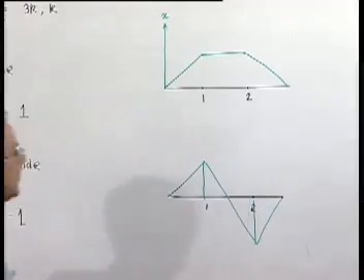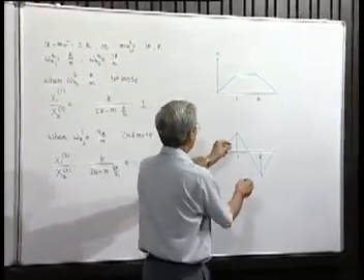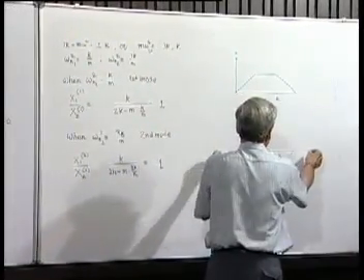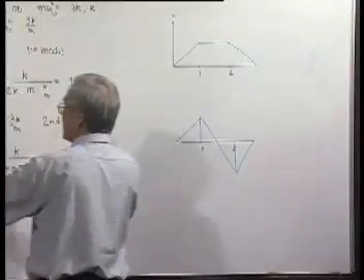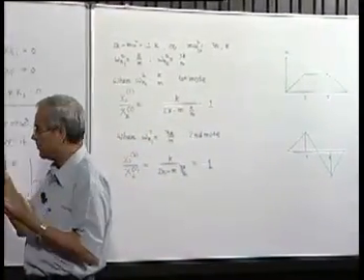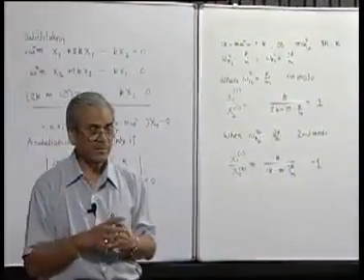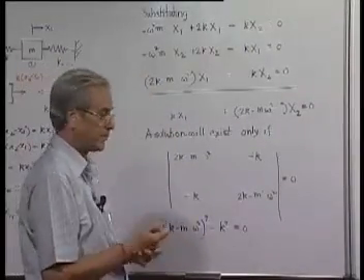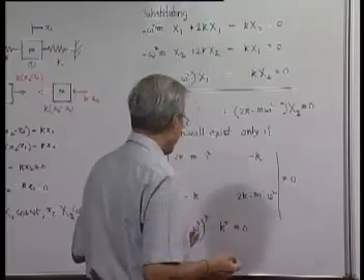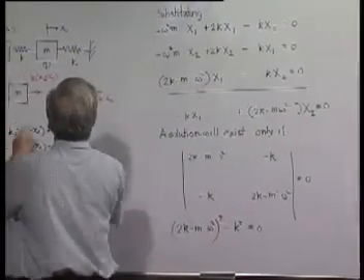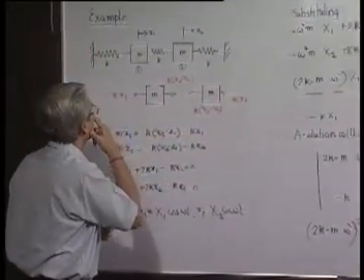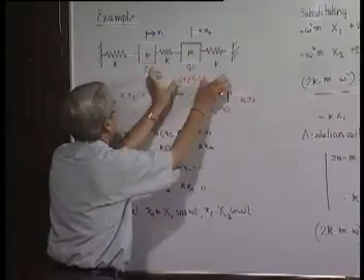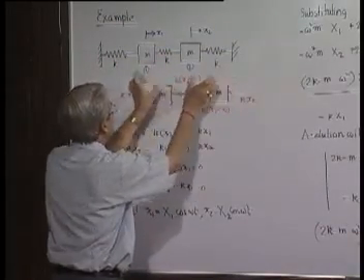In the second mode, obviously we find if x1 is here, x2 will be equal and opposite. That will be the mode shape. Now remember again that it is only these two bodies that are moving like this, because movement is in this direction.